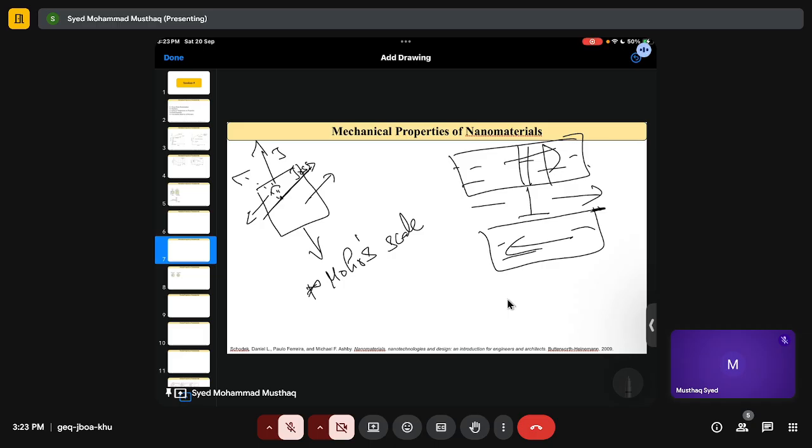Again, we had all this pain to understand this Hall-Petch correlation, but still, this Hall-Petch correlation cannot be applied to nanomaterials. And I hope you all know after seeing those lectures, because if the grain is very small, then how can you accommodate the dislocations? Because the line defects are lengthy, right? They are very long.